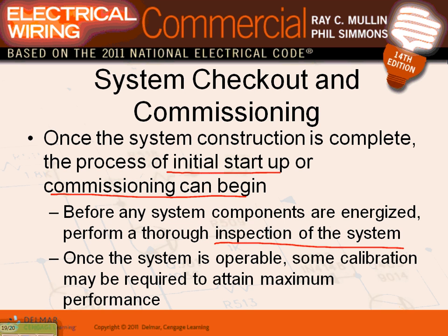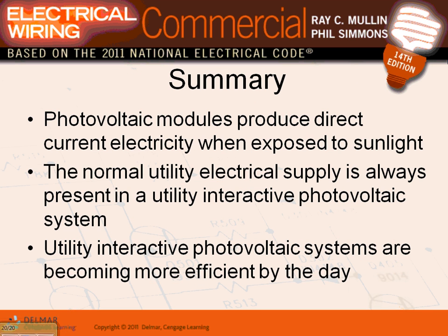There are a whole lot of things you need to do, guys. Inspect it, and make sure the system is operable. You have to do some calibration to attain the maximum performance of your system, because you might have to readjust your inverter, or, I hope not, readjust your array. So there are certain things you have to do in commissioning and testing, typical for a major system.